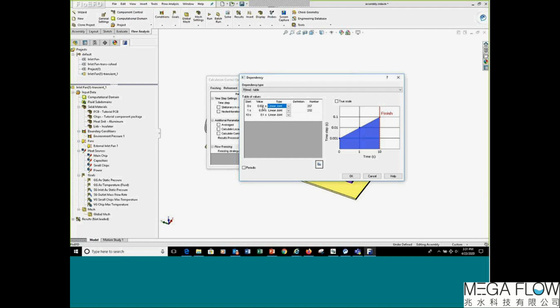So I'm forcing the time step to increase quicker, obviously within less time frame, and start a little larger. But again, for this test model, it's okay. I would probably still start at e to the -5 or -6. That just makes more sense. It's better for the calculation, and you get more accurate calculation in general. But for this case here, just to show for the test, I would do something like this.